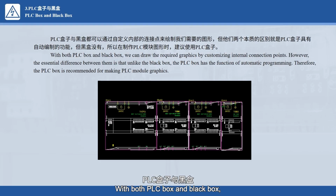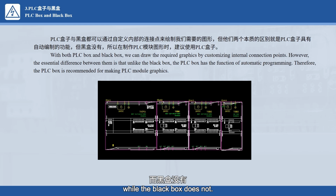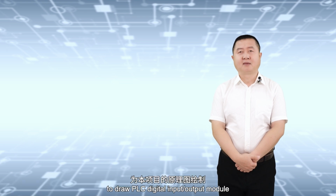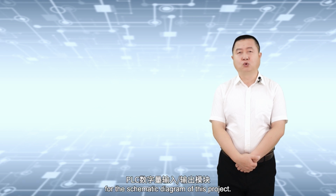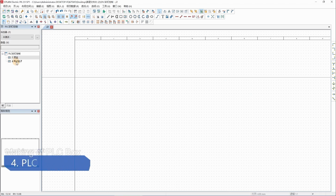With both PLC box and Blackbox, we can draw the required graphics by customizing internal connection points. However, the essential difference between them is that the PLC box has the function of automatic programming, while the Blackbox does not. Therefore, it is recommended to use PLC box when making PLC module graphics. Let's use PLC box to draw PLC digital input-output module for the schematic diagram of this project. The specific operation steps are as follows.